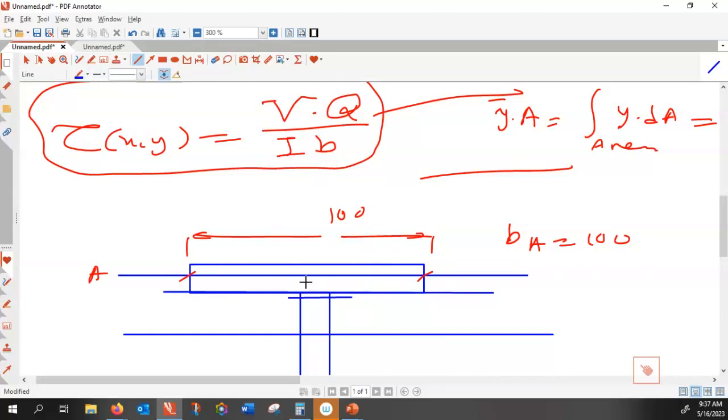So you expect to have a shearing stress discontinuity when you are near that point here. And that makes sense. In that section, suddenly at the top, the shearing stress is large because the area is small. When you go lower, the area becomes smaller, the shear stress becomes large. So if this is a very risky area, you might have crack growing here. That's a stress concentration. When suddenly the stress grows or becomes smaller, that's a stress concentration. That's where you might get this one to collapse.